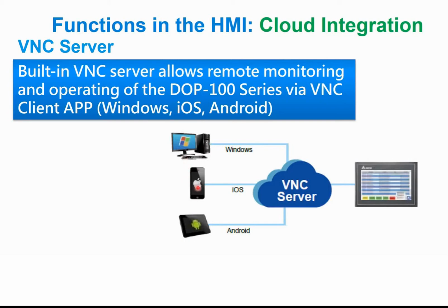If you are using iOS, an iPhone, an iPad, or any smart device with the iOS system, you can also use it to control the HMI. If you log in via this VNC server, you can control all the screens in the HMI. With this function, you will have a virtual HMI on these devices. Everything you can do on this physical HMI, you can do on the devices you are using, and Android is also supported.